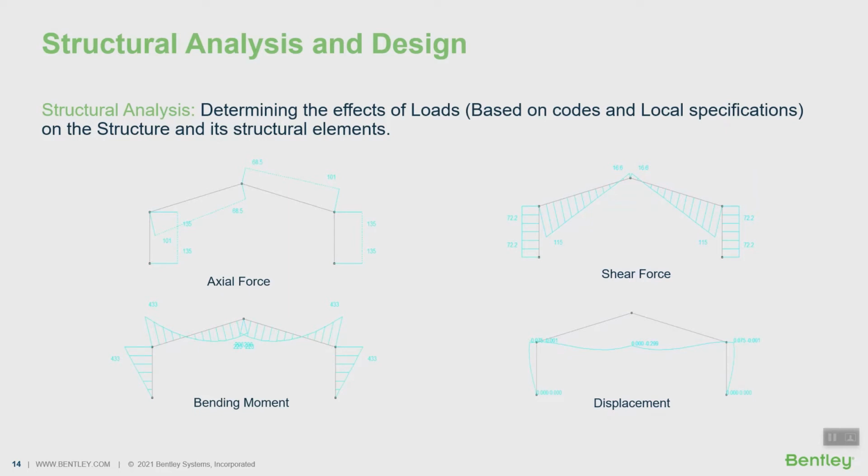Now that we have some idea of what a structure is, let's understand what analysis of a structure means. Structural analysis simply means determining the effects of loading on a structure and its structural elements. Loads are the external forces acting on a structure, which are typically applied based on codes and local specifications. These loads will generate effects like the internal stresses in a structure, that would be axial force, shear force, and bending moments. Also, the structure will undergo some displacement due to the external loading. A structural analysis aims to calculate all of these effects.